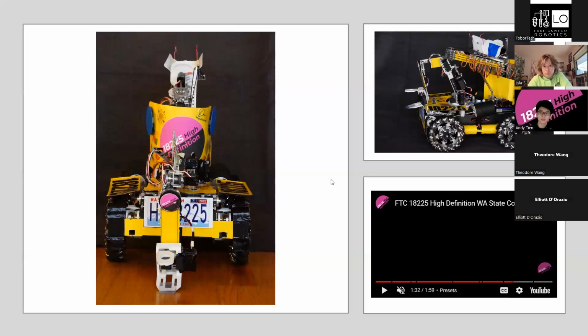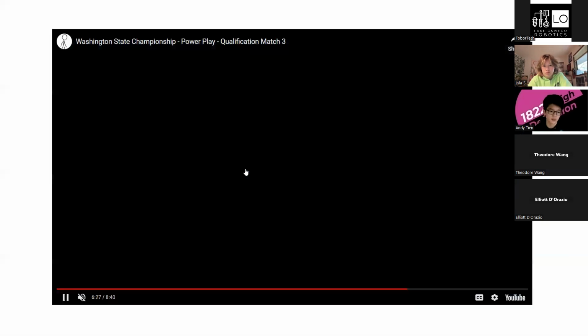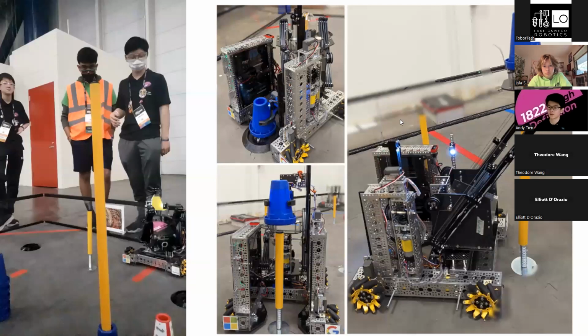So for the last season, how did we manage our wires with our vertical sliders? One of our main design considerations, and how we limited the room for error in our robot, is that if you look, there are no wires on the delivery. The delivery is a completely passive delivery. So that not only mitigated the need for wire management, but it also prevented the wires on the delivery from getting caught on anything during the delivery process.